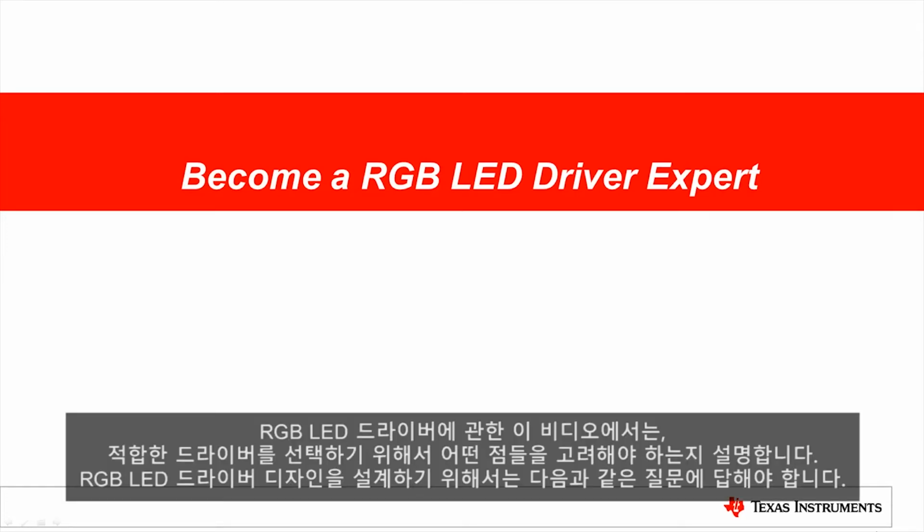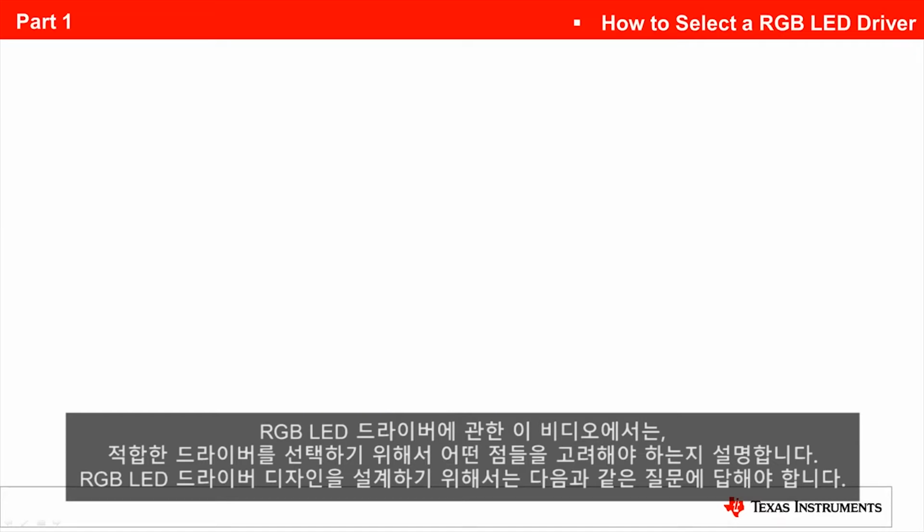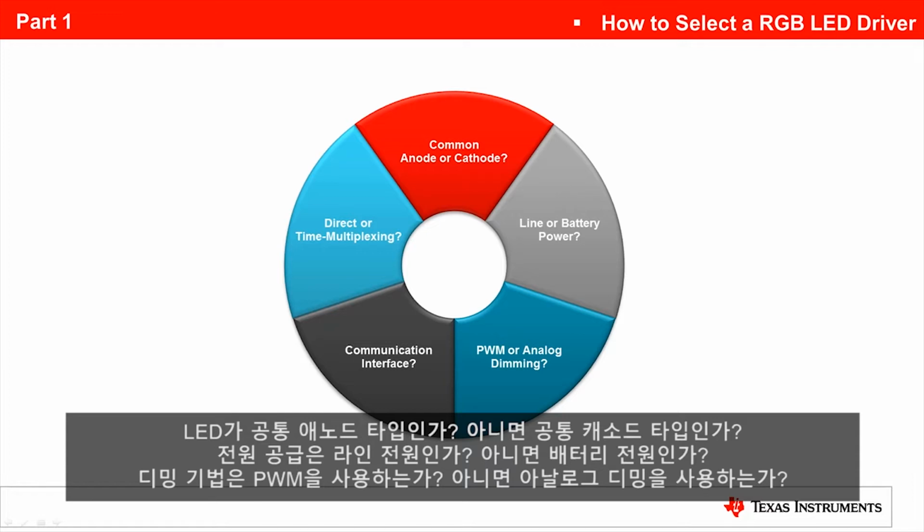In this RGB LED driver training, we will explain key considerations for how to select the right driver. When you start an RGB LED driver design, please make sure you have asked yourself the following questions about your applications. Is the LED a common anode type or a common cathode type?